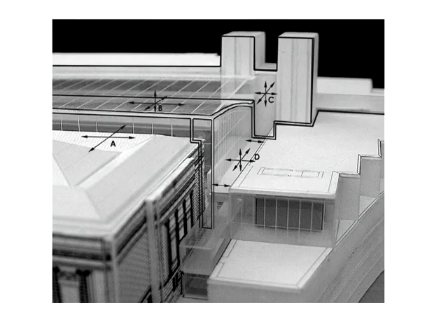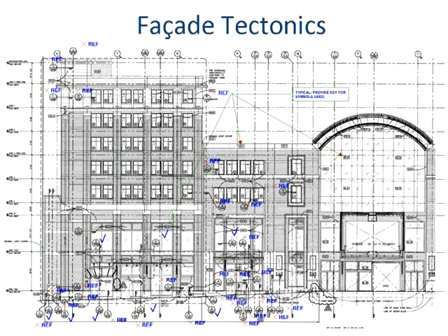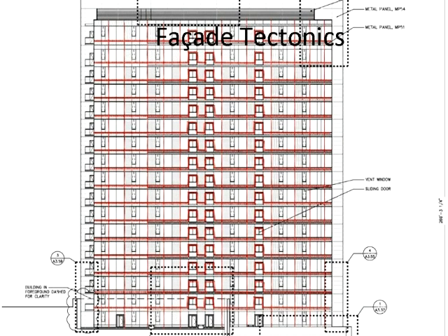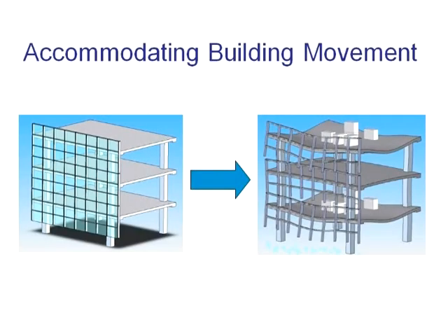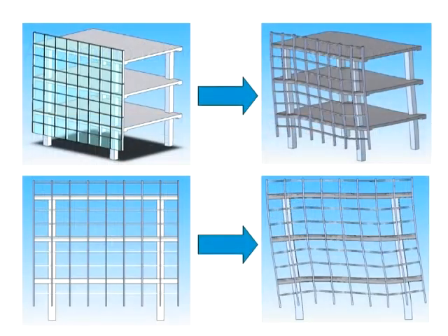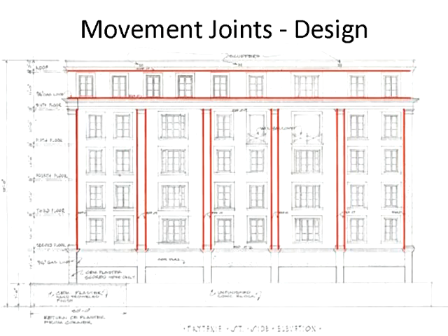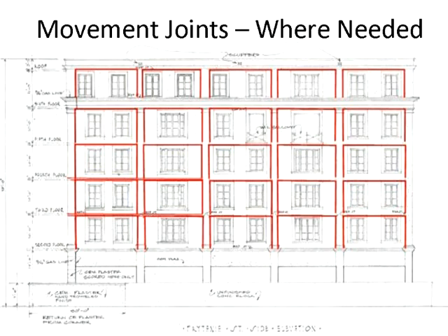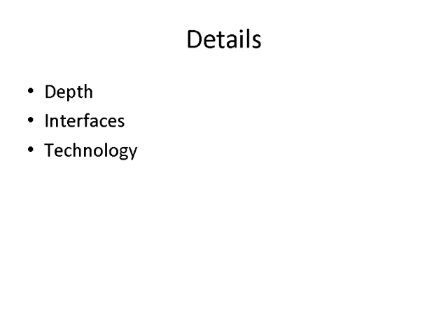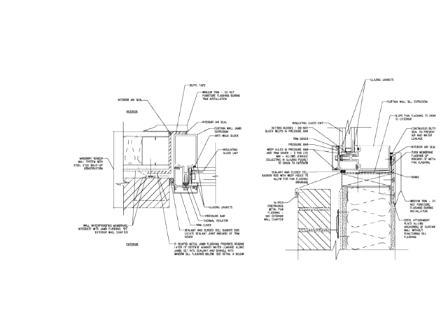Now, in order to cross and negotiate movement joints successfully, you need to find them and quantify the movement. Again, we cannot hit a target that we don't see, so we have to visualize it by drawing it on facades. There are 3 degrees of freedom: up and down, left and right, and on some projects back to the front. Your structural engineer needs to tell you what is the quantity of movement in those movement joints, and you additionally need to add the control joints to the equation. Only at this point do you have sufficient information to be able to start drawing details.